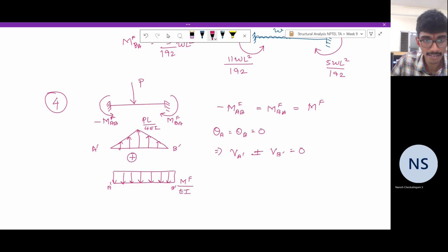The shear force arises if there's a reaction, and the reaction is required if the loads are not self-equilibrating. If the total upward force is equal to the total downward force, then there is no need for the support reaction, and if the moments are balanced, there is no need either. So the moments will be balanced since the loading is symmetric, but in order for the forces to be balanced, we can equate the areas under the loading.